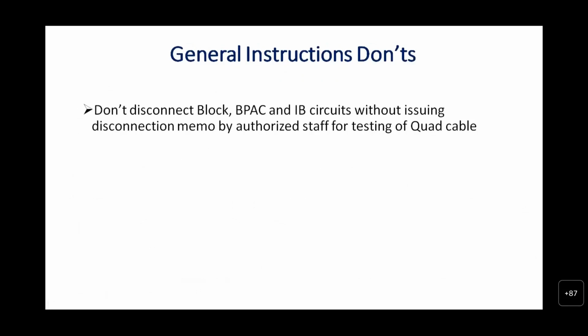Don't disconnect block BPSC IV circuit without issuing a disconnection memo by authorized staff for testing quad cable. Here, authorized staff means signaling staff, JE or ESL.